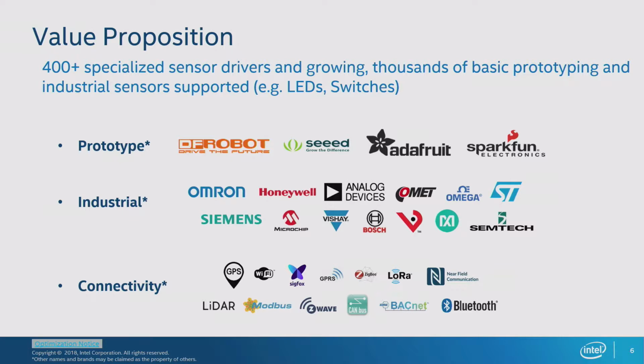And for connectivity, we actually have a bunch of options as well, both wired and wireless. It really depends on the industry. So for instance, if you were to deploy a solution in automotive, you would maybe tend towards a CAN bus, and we do support some of those radios, some of those controllers. But then if you wanted to go over the radios, you could do things like LoRa, Zigbee, wireless, of course, and others.